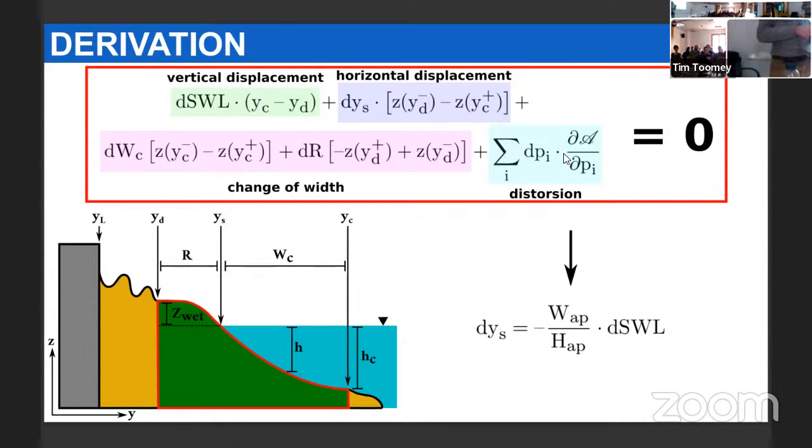Yes. Very basic question. How do you define this actually? Yes, so for the submerged part of the beach, we usually consider the critical stress for sediment mobilization. So you consider the minimum force at the bed of the beach that you need to start mobilizing sediment. It depends on a set of parameters.